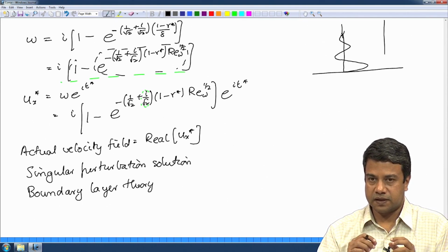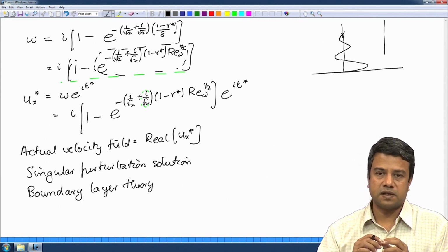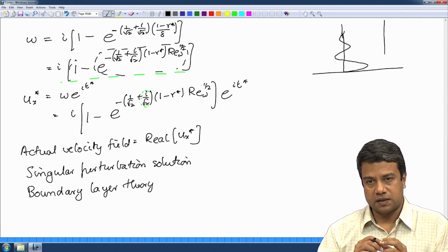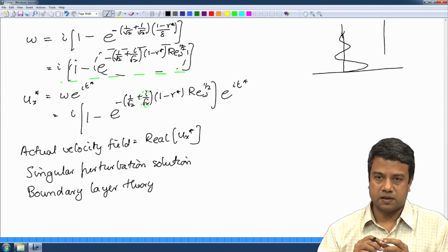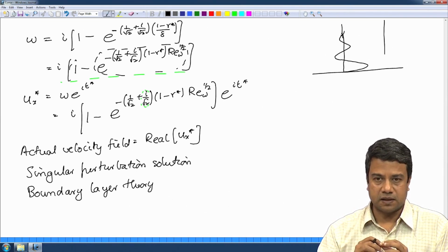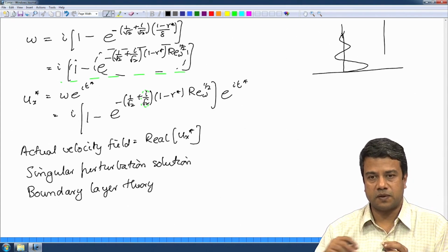And that thickness of that region is determined from the condition that inertial and viscous forces continue to be of equal magnitude within that thin region, even in the limit as the Reynolds number goes to infinity or the Peclet number goes to infinity. The boundary layer thickness delta will be some power of the Reynolds number or the Peclet number. It will not in general be minus half as in this case, it could be a different power.